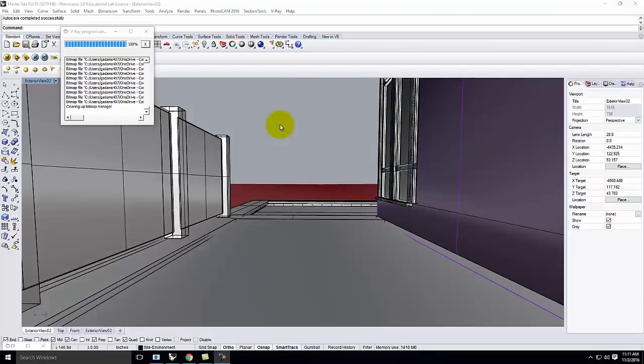So today we start on exercise 223, which is not quite a nighttime rendering. We're getting there, but we're going to switch and do an interior daytime rendering. So the assumption would be that you've already installed your HDRI background imagery, you already have your sun set, and you're basically ready to go because you did an exterior daytime rendering already. We're just switching our view to be on the inside.